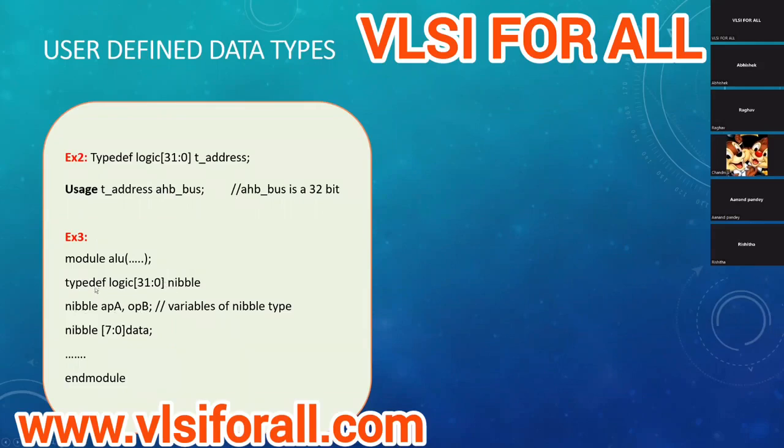Similarly, you can create a typedef logic 31 down to 0 as nibble, and use that typedef in different parts of your design. So it's more readable, and it helps your design to be more portable also. You'll really understand this when the designs are complex and used across projects, and some engineers code it and then leave, and someone else comes in. If you use these coding practices, it will help you and anyone who's replacing you to understand the design or the test bench quickly.